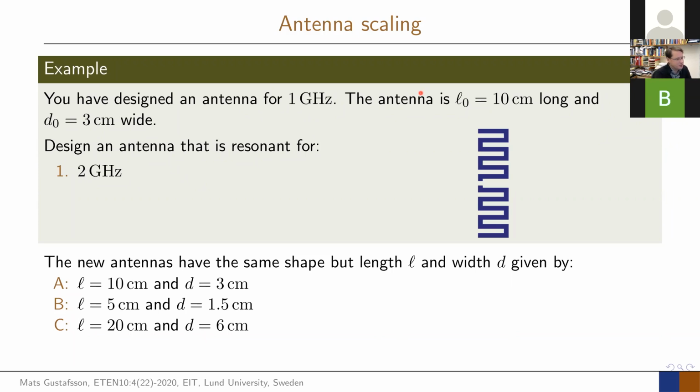That is how you measure it. So if you made a dipole antenna for 1 gigahertz, and you want it for 2 gigahertz, just make it half the size. And in many cases, maybe there is a ground plane or dielectric thickness of some slabs that you cannot change. Then at least you have your initial design done, and then you can optimize around that one. But in all of these cases, we really talk about antennas and dimensions measured in wavelengths. That is the natural way of looking at the dimensions of antennas. And scaling is then really powerful to change these things.